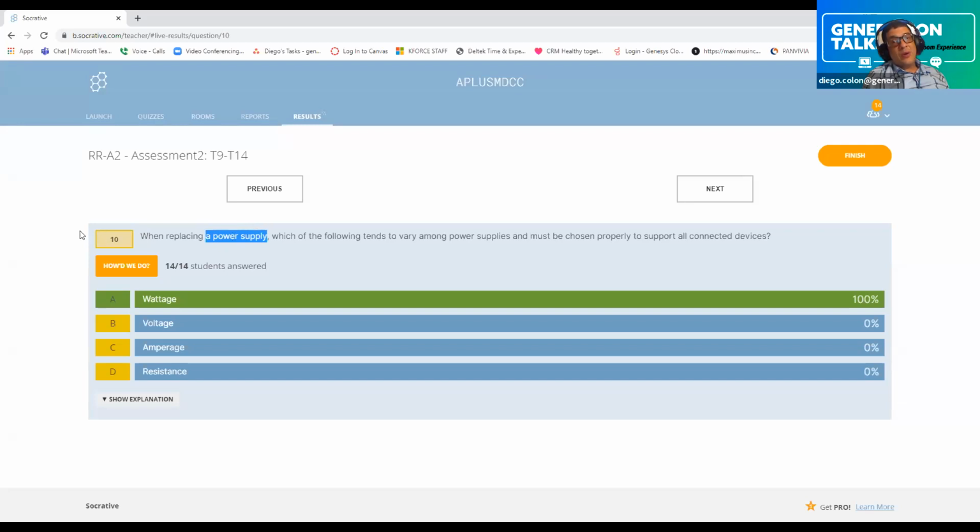So we do agree all of them are going to be taking so many volts. All of them are either taking 12, 5, or 3. And all of them have a pull, like we said, how much pressure is coming through that hose. So how much pressure does that puppy need? If I don't have enough, that PSU, power supply unit, will basically not power up everything, and we get a black screen or something happens. So we need to take note of the wattage, which is the voltage the unit is using times the amperage, which gives you the total wattage.